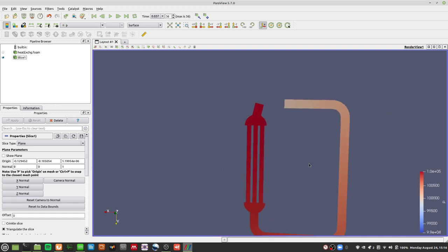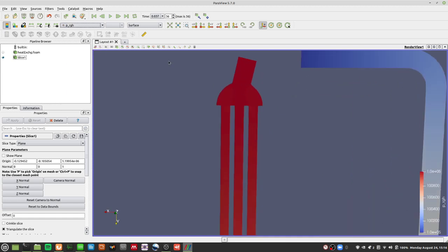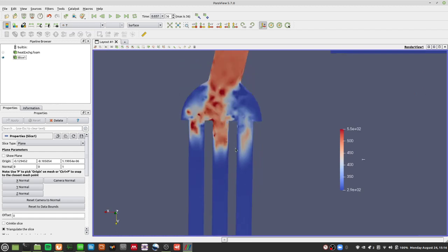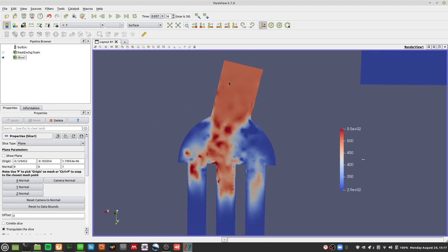And if I include the hydrostatic component there, you'll see that the pressure profile is more or less the same. So we can see that the problem that's causing this, I guess, is that the air is coming from a very even geometry like a cylinder, and suddenly it's going into this top part of the heat exchanger, which is a sphere, and then something wonky goes on with the solver, and suddenly the temperature goes very wonky. Okay, so now you can see that in action.